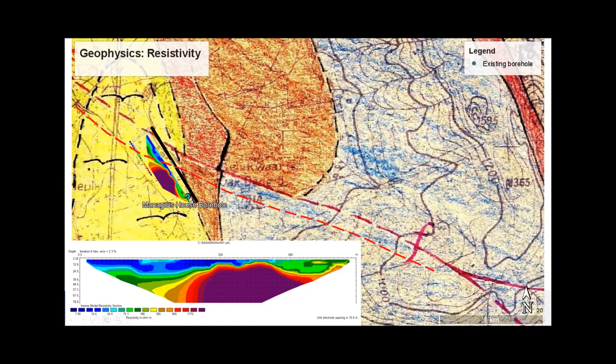Then we can plot the hydrocensus borehole on the resistivity profile. We can see that they drilled into that hard rock. That's probably why it's low yielding. So what we did is we decided to site the borehole in that faulted zone, but we moved it all the way to the east as far as possible so that we can avoid impacting the area that needs to be cultivated, and so that we can avoid artesian conditions.